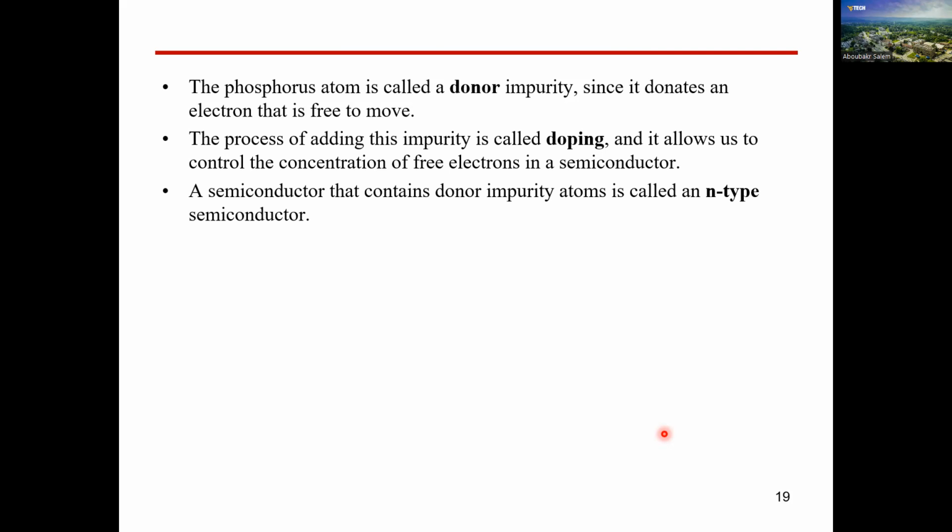Why N-type? Because in the case of phosphorus with silicon, we have one extra electron, so this is negative charge, so we call it N-type. We may have more electrons, according to the material we are doping into our semiconductor material. The doping process determines the conductivity and the currents in the material. Why? Because as we mentioned, the more concentration, the more current can flow and conduct, or connect any supply to a load, as if it's a conducting material.